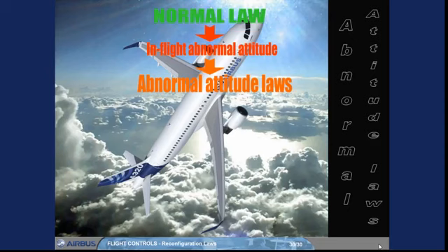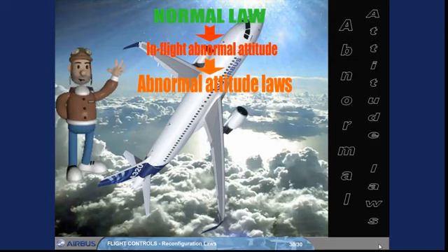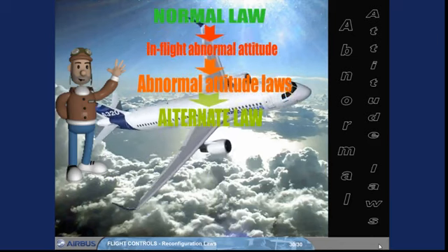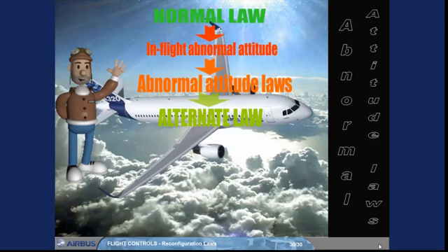This is a safety feature to ensure that the flight control computers will never prevent the pilots recovering from an abnormal in-flight attitude. The flight control laws operate in alternate law without protections and stabilities, except for load factor protection. After recovery, controls remain in alternate law, without protections but with auto trim. There's no reversion to direct law when the gear is extended.